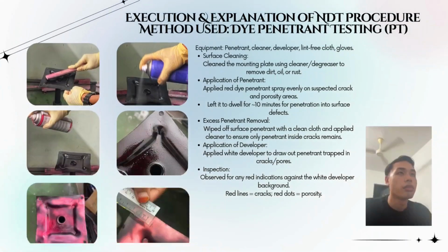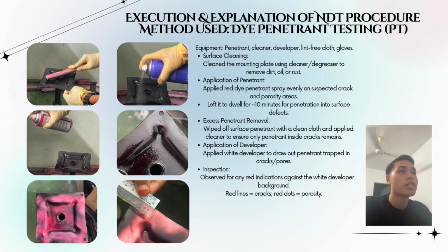Okay, my name is Muhammad Alif Akmal. I will explain my part, which is the execution and explanation of the NDT procedure method used for my project. We use dye penetrant testing, which means PT. For the equipment, number one, we use penetrant, cleaner, developer, clean-free cloths, and gloves.